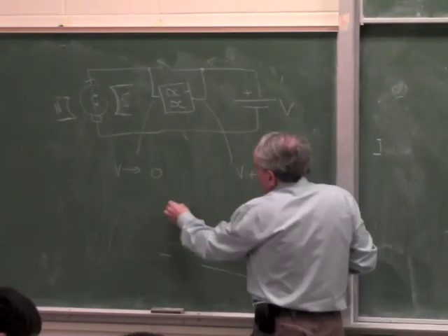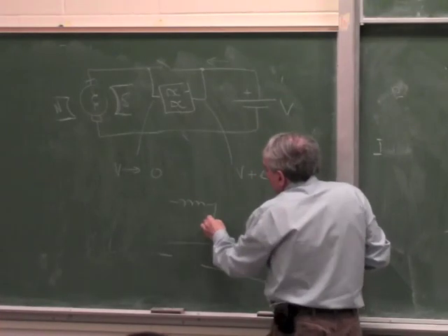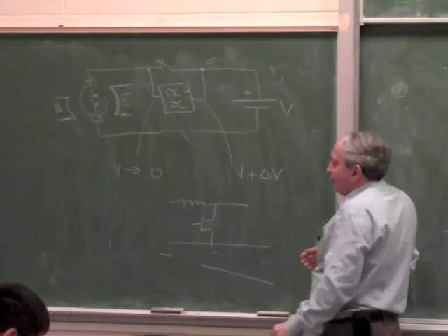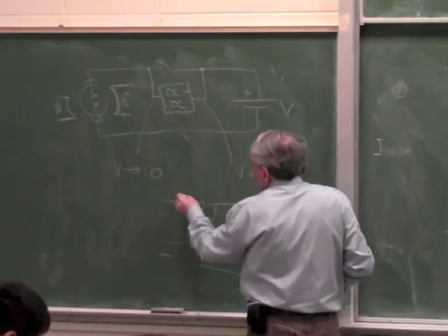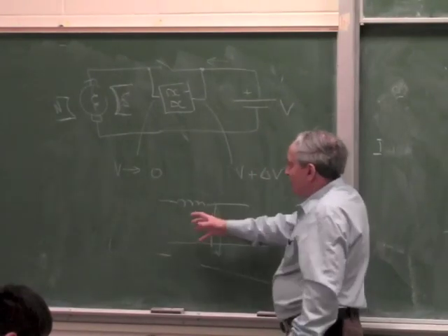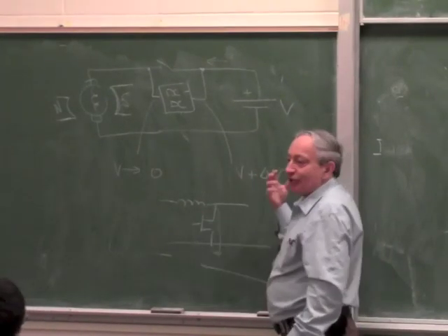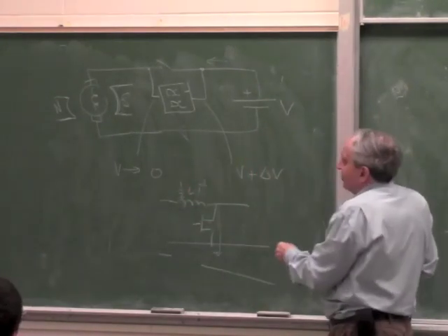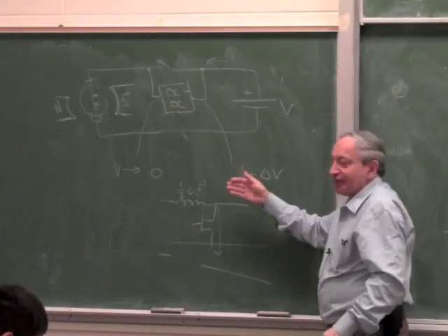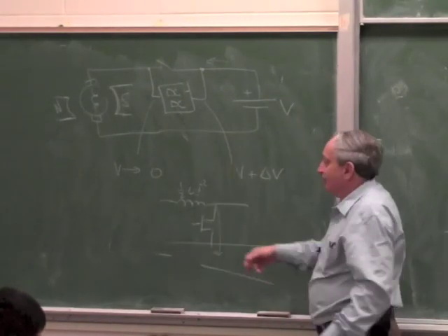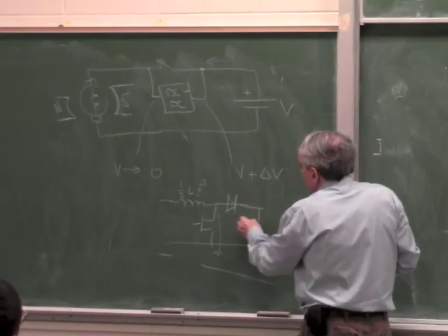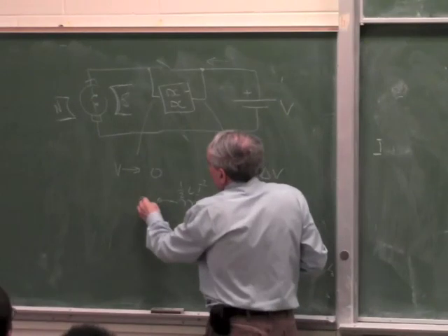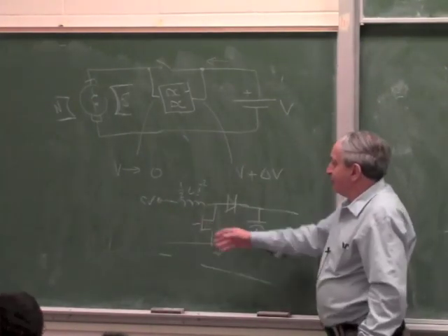If you take a coil and you run it through a switch, let's say a FET, okay? If you close this FET, the current will flow to ground. If you open this FET, the current wants to keep flowing because of the stored energy, 1/2 Li squared. Because the current wants to keep flowing, the voltage here will become very high. It's trying to break down the switch. So now you can put a rectifier here and charge it up. This way, even if this is, say, 5 volt, depending how fast you open the switch, this could be 1000 volt.